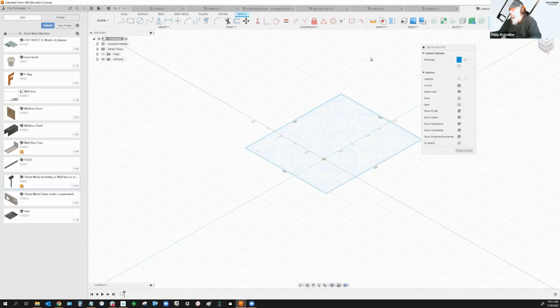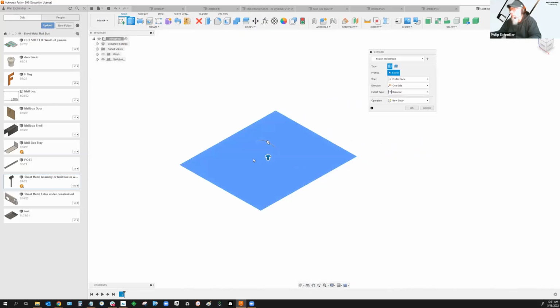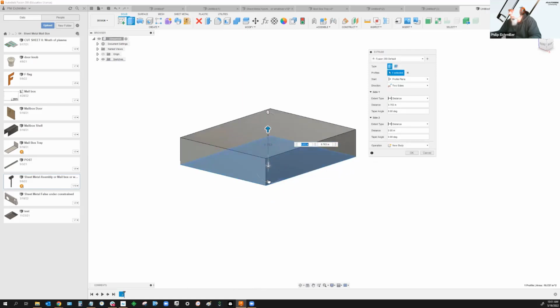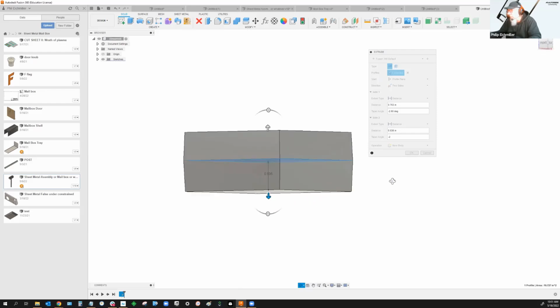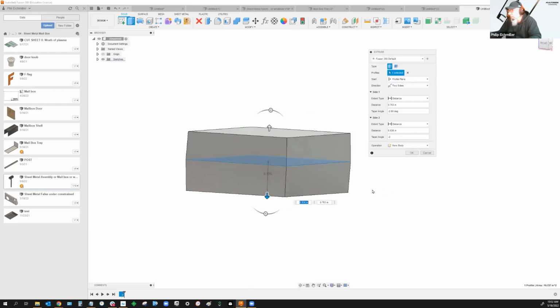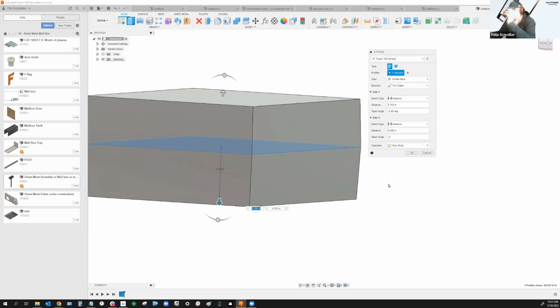You're thinking about parting lines, right? So if I'm doing this extrude, oops, of course it picked it for me automatically. I'll do 2 sides, bring this one up, bring this one down, and I'm going to add a taper angle. So -2 there and -2 here, right? Just by doing it this way, this is just a simple extrude, right? But if you're doing this workflow, you're already thinking, well, that's my parting line, right?